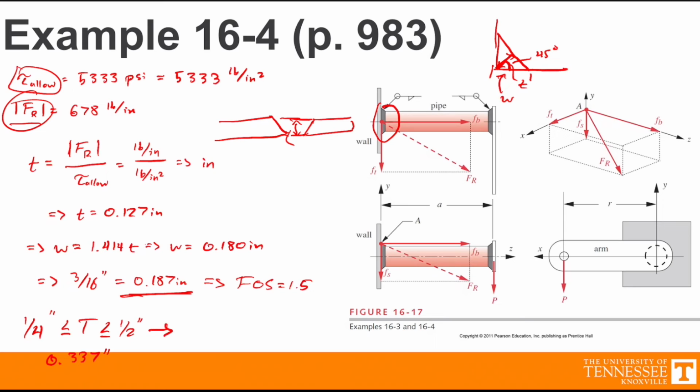And for that, the minimum leg length for a fillet weld is 3/16 of an inch. So that perfectly falls within what we need, what is designed by the governing bodies of AWS and AISC, that they've said is the proper size of weld for this type of situation.